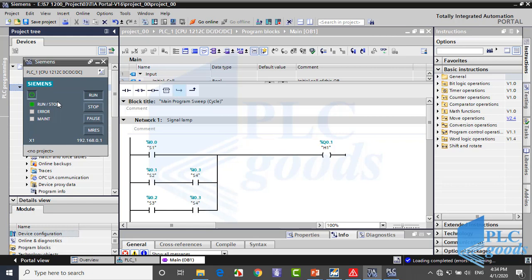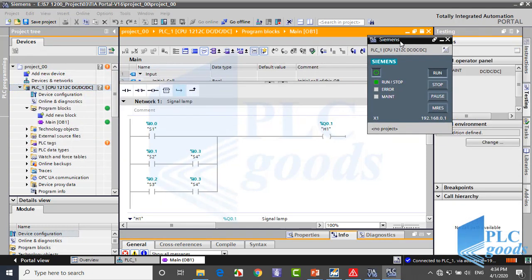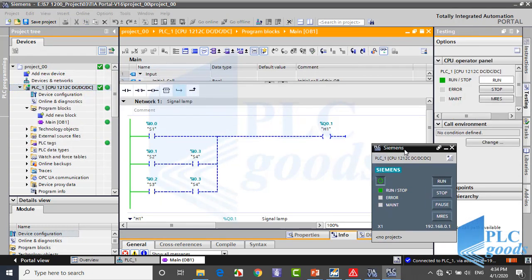Now, the latest program on my computer has been transferred to my virtual PLC, which you see on the left. I want to see what happens in my virtual PLC program, not in my TIA software. So click on this glasses icon. When I press this icon, TIA software shows me the PLC program which is connected to TIA. So, the working window is changed a little. For example, the color of this window is changed to orange. The instructions on the left side are gone. Instead of that, a CPU appears here. And on the left, some green circles appear.